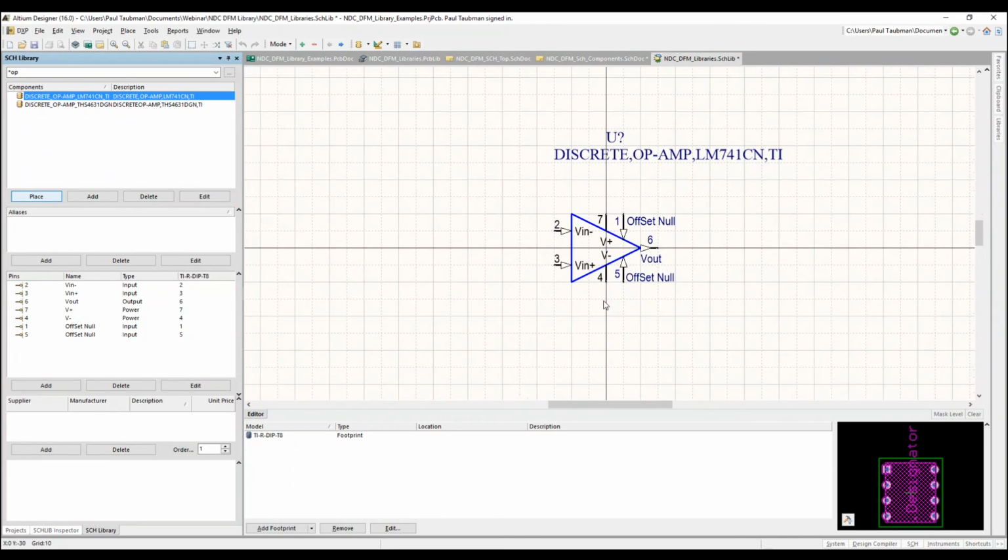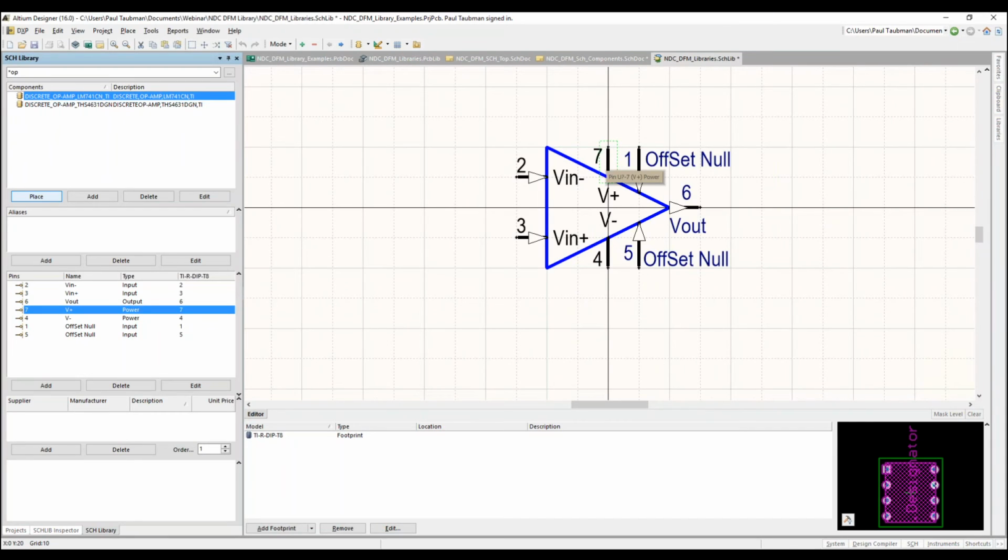Now, Altium does use, by the way, a pin setting. Its default pin length is 20. I think that's way too long, because when pins are really long, that means you've got a lot of wires that have to swing kind of wide in order to come in. So I think a setting of 10 works just fine. And as a side note, because we've done cable work in the past, sometimes you need to have a pin length of 0, and it just becomes a dot, and it will work. You can still connect up to it, but it just looks like a dot. So you can certainly do that.